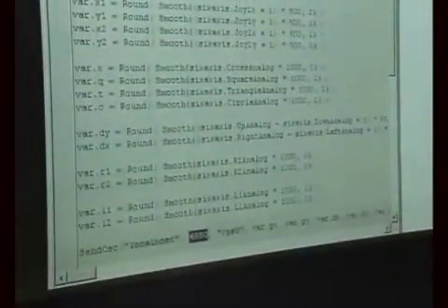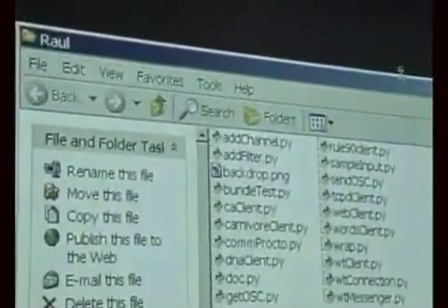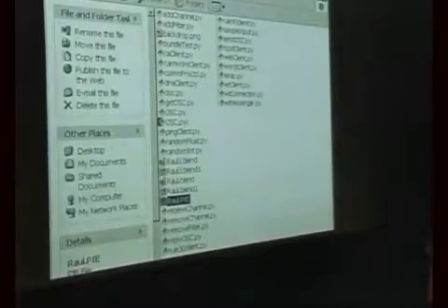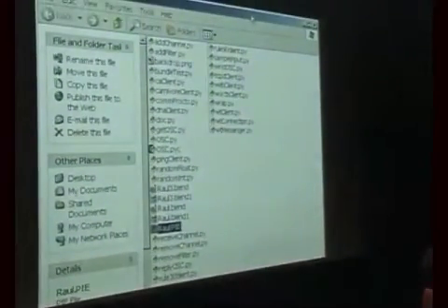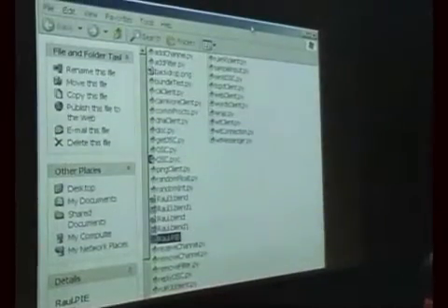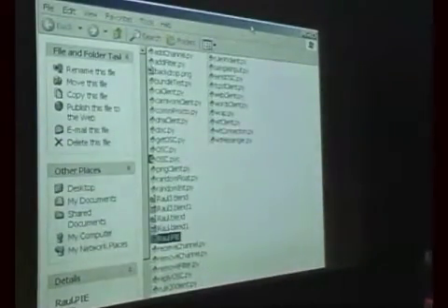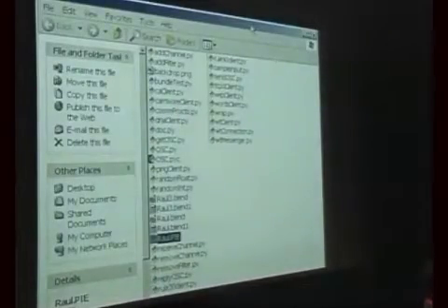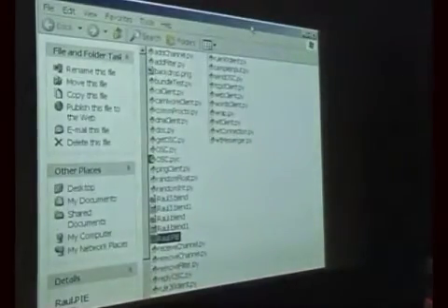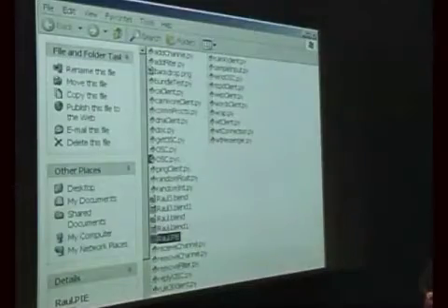And there you can see it's working. This is just a readout. Yes, because OSC converts every number into a Unicode character. And if it's a whole integer somewhere in between those boundaries of Unicode, then it only needs to send one character, and it goes faster.